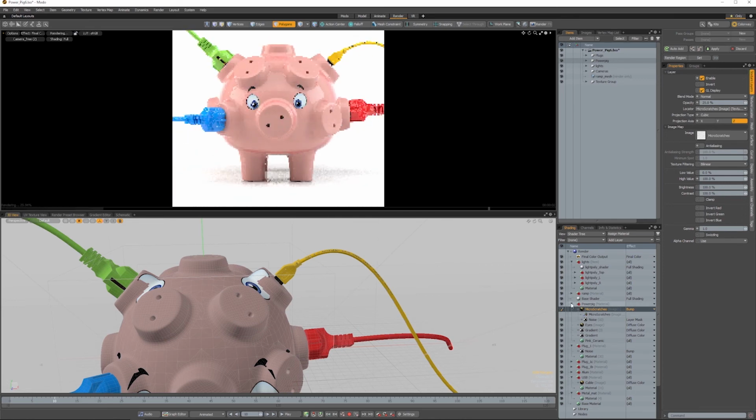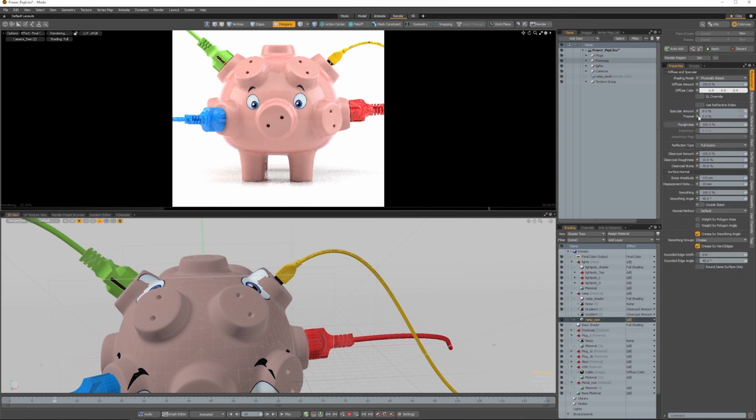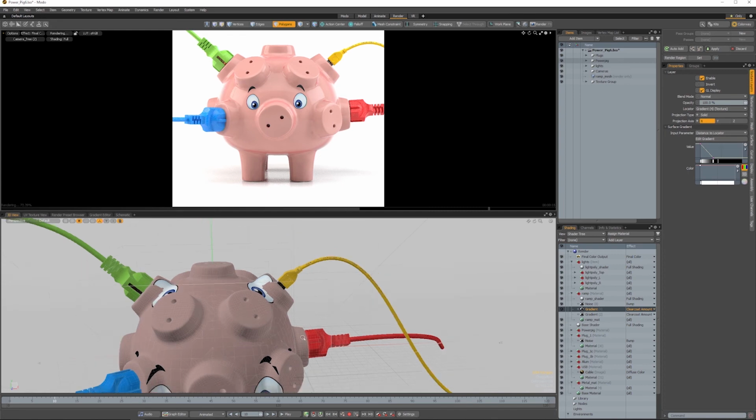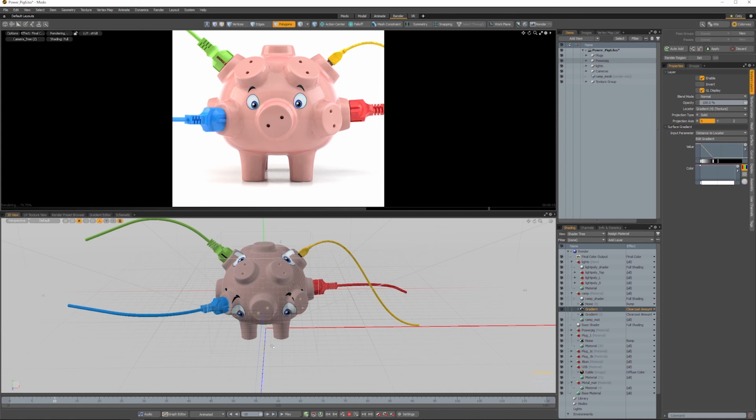Now going to the ground. So the ground is a white color, simple, nothing special there also. What I did was I added a clear coat gradient here as input parameter distance to locator. So I have a locator here on the 0, 0, 0, and with this I'm creating a clear coat amount, that if I show you the effects here, you see the clear coat is only acting here and it's decaying from the center where it's 100% intense, and going out it's fading to 0.